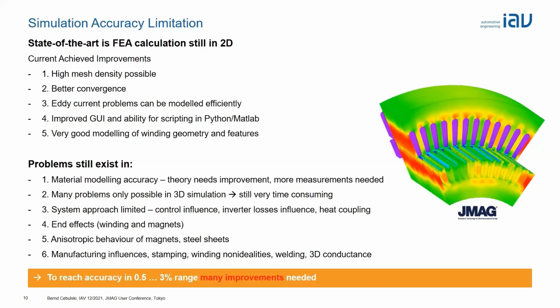Especially with the latest version, there have been many improvements to model 3D geometries of hairpin windings, but also round wire windings, which make it quite easy to make a real winding in several minutes, I would say. Before that, you would have to model this with very expensive CAD systems and import the geometry into JMAG, which incorporates a lot of trouble.